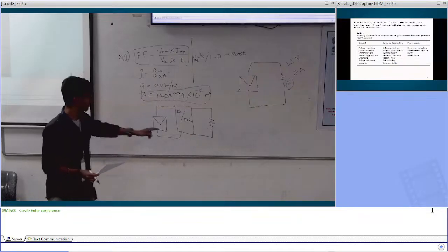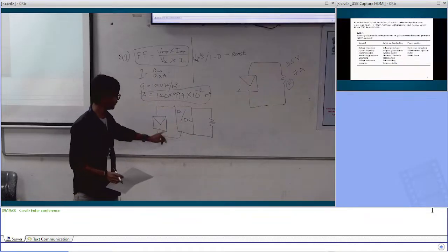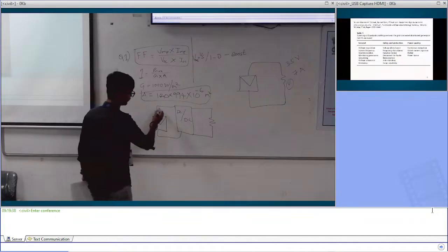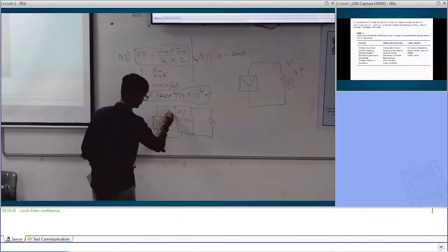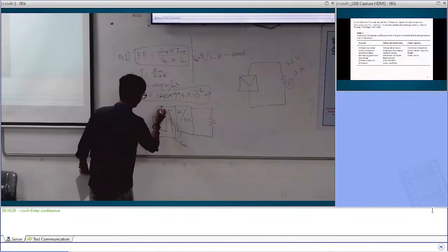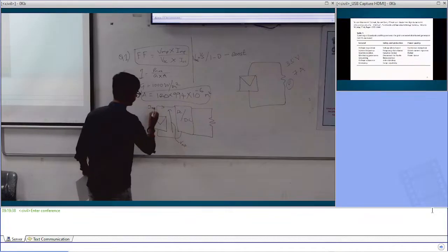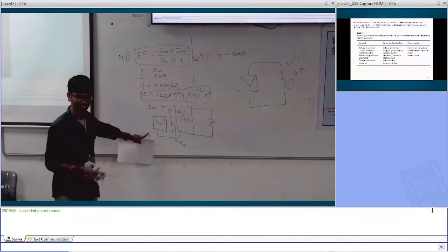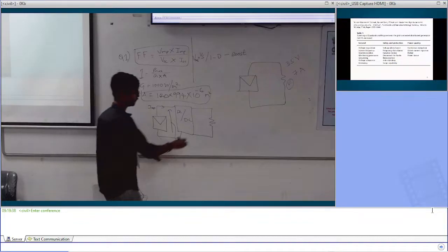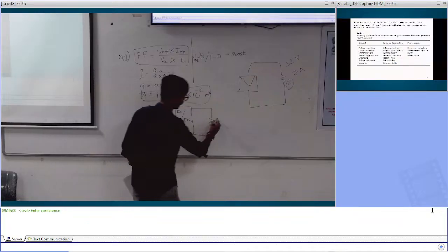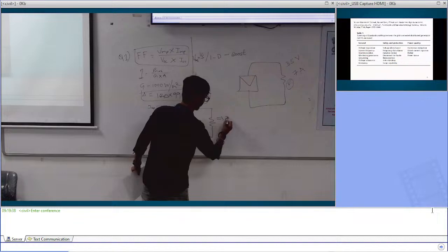Now a boost converter is connected with the PV panel such that now the PV panel is working at MPPT. That means we are extracting maximum power from the PV, that is this voltage as VMP and this current as IMP. If we are generating maximum power from the PV panel, then the same amount of power the resistor is absorbing. So the resistor is now absorbing the same amount of P max power.